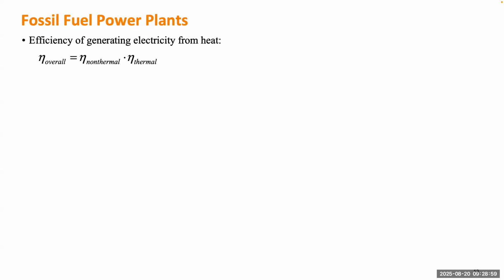Non-thermal efficiency depends on the design of the power plant, but thermal efficiency depends on physical laws. And maybe there's a certain limit we can hardly go beyond. That limit is called the Carnot efficiency. So the thermal efficiency, theoretically speaking, cannot go beyond this Carnot efficiency. A Carnot efficiency is the efficiency of a heat engine, which is a very ideal heat engine.